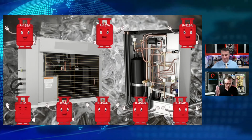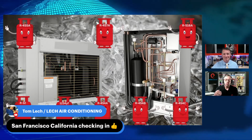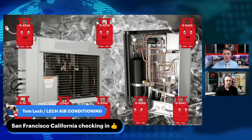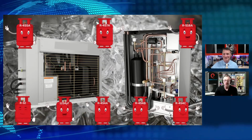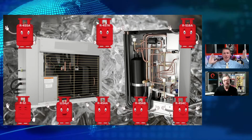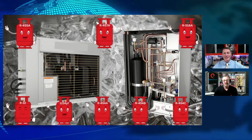Right. When we were switching from 22 to 410, the rest of the world was switching from 22 to 32. Our building codes and our applications just weren't ready. They weren't allowing for flammable. So all we did was take 32 and add some flame suppressant to it, R125, and it became an A1 refrigerant, and 410A was born. Everybody was happy, except for the global warming people. R125 is pretty bad, right? Very, very high.